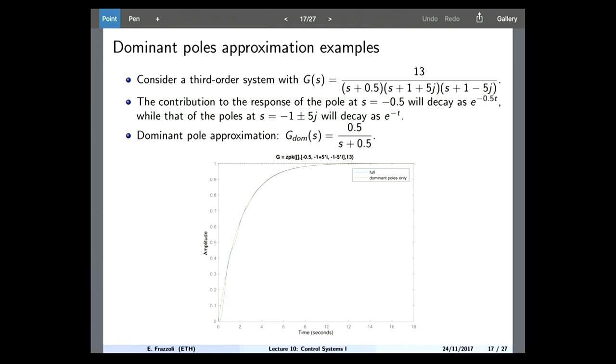But essentially the point is that if you want this to approximate this, at least they should have the same behavior at steady state, right? So just make sure that the Bode gain matches and then delete the factors that you don't need. Okay? Other questions? Yeah.